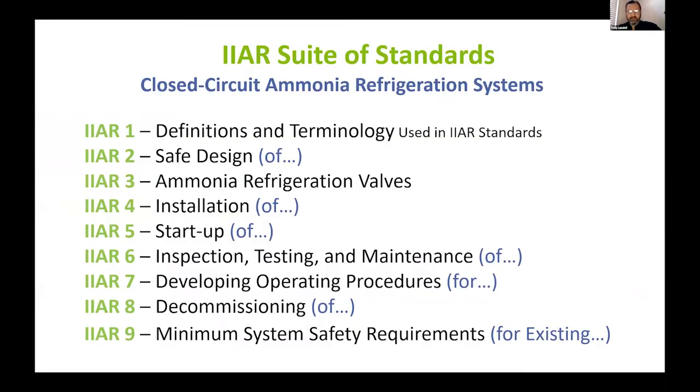What the IIAR has developed is a suite of standards. And these are for closed circuit ammonia refrigeration systems. IIAR 1 is the definitions and terminology used in the IIAR standards. And then the next is a safe standard for closed circuit ammonia refrigeration systems, which is IIAR 2.